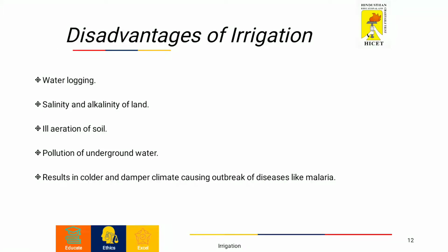The disadvantage of irrigation is that excess irrigation is going to decrease the crop yield, because if you put a lot of water, the crop roots will get submerged continuously and the water itself will act as an oxygen barrier, so that the roots cannot take any oxygen from the soil and thereby definitely reducing the crop yield because of oxygen stressed condition. Then chemicals such as pesticides, fertilizer, herbicides and salts can be leached into the groundwater or to the nearby surface water areas.